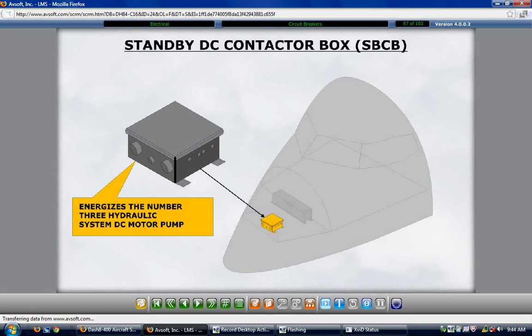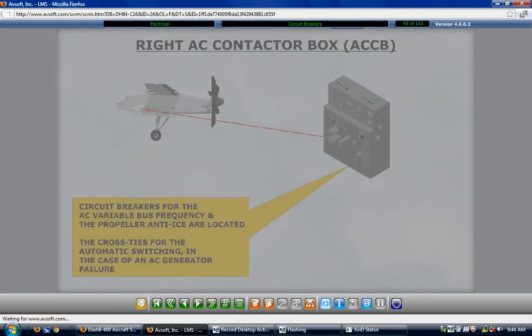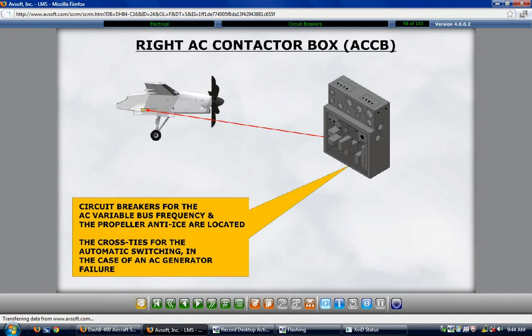The wardrobe at the forward area of the cabin has additional circuit breakers. The breakers in the wardrobe are for maintenance and avionics. The circuit breaker panels at the galleys are for galley equipment heaters and area lighting. Each circuit breaker is referenced and identified by the panel it's located on, the electrical bus it serves, an identification label on the circuit breaker panel where the breaker is located, and an alphanumeric cross grid for locating the breaker.